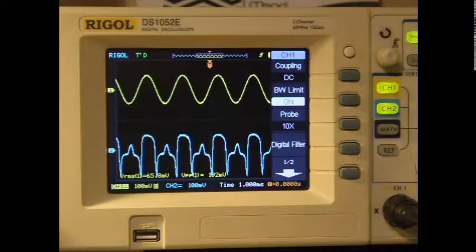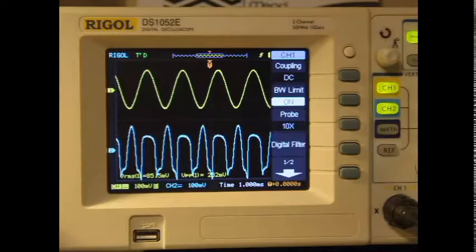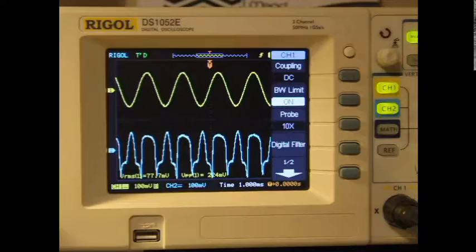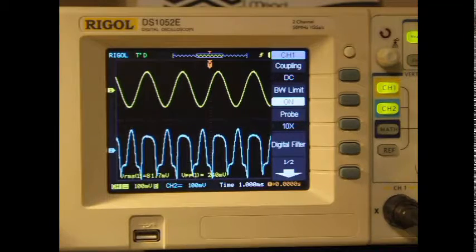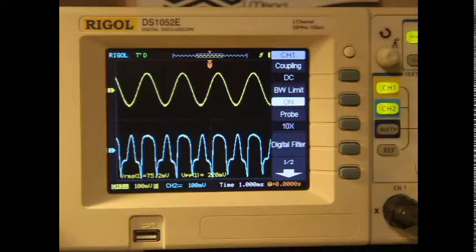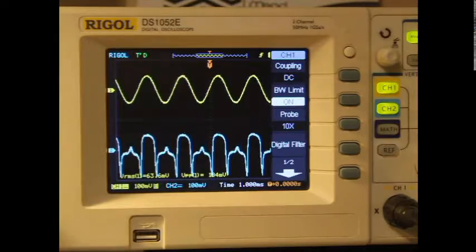The Octomotron instead just uses a JFET, which is set up as a split load phase inverter. It's a different way to do that. I think when you overdrive that FET all the way into cutoff, once that FET cuts off, there's internal negative feedback that stops happening because it can't move anymore, and so you get a little increase in gain. So that nipple is this increase in gain that happens when the FET cuts off, I'm pretty sure.